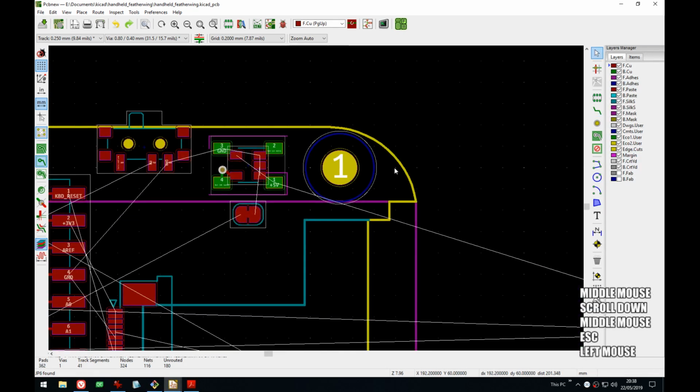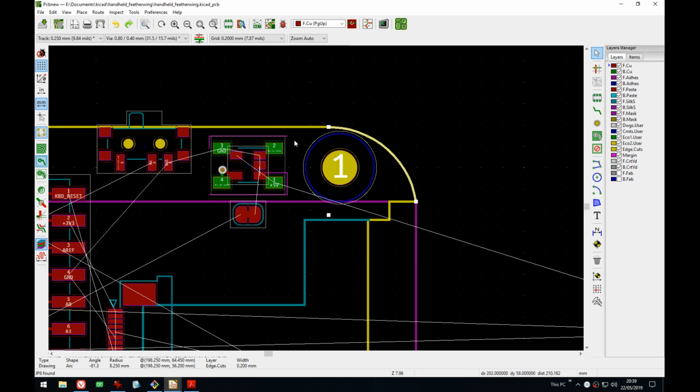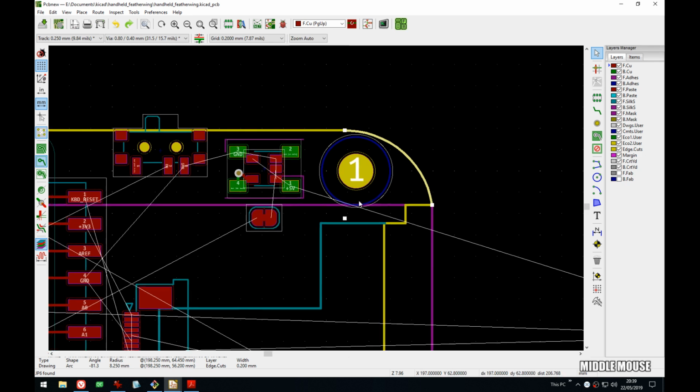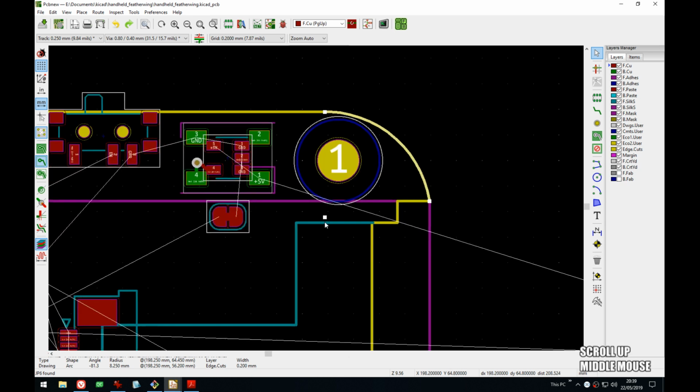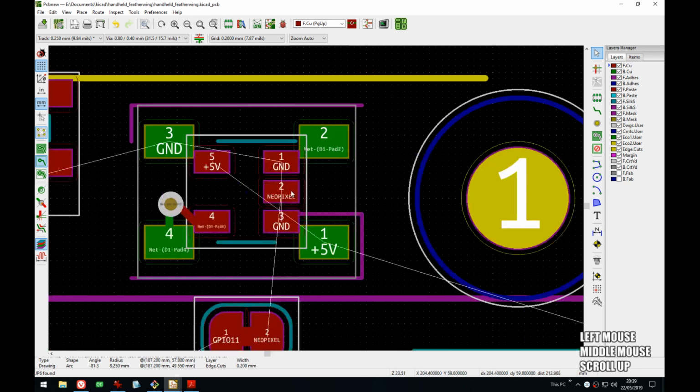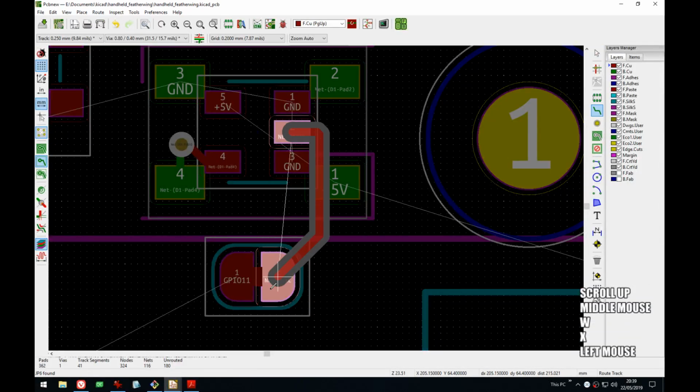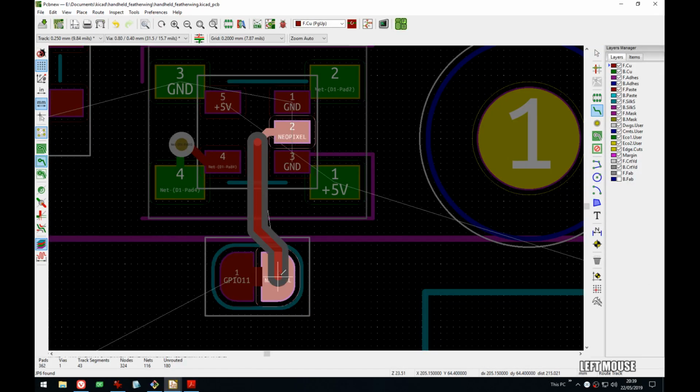that somehow... oh, what's the word? The arch here, the circle, the arc. The arc seems to bug out and KiCad thinks it's a full circle and the keep out is on the full circle of the arc. But I thought that was fixed way back. So right now to actually get around this, I can just do this, but that's super silly.